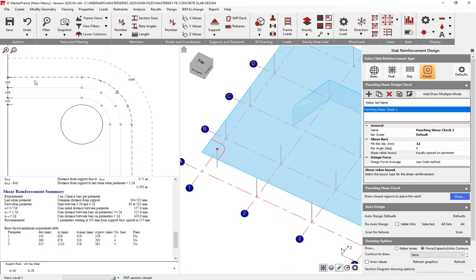So you can see the perimeters noted here as your 2D effective perimeter, and then you've also got the outer perimeter, all in line with the code designations. So we are doing Eurocode design here. This will work for British Standard design also. But I can say that I would like a radial layout. Obviously that means you've got more bars in here, but a slightly more convenient arrangement of reinforcement to place. And it may be that's something that you can provide using shear rails if you want to go for that type of layout.